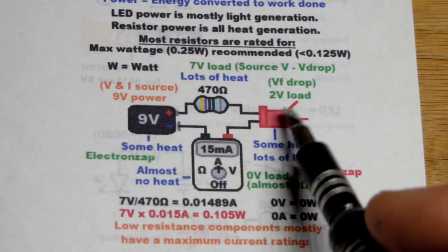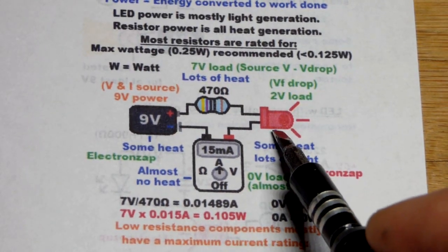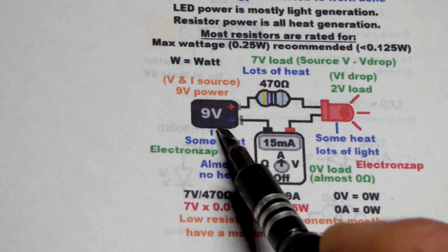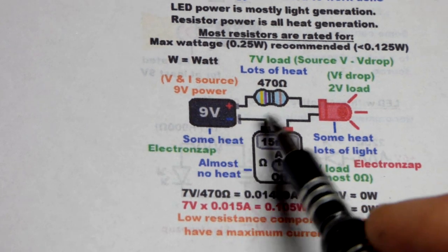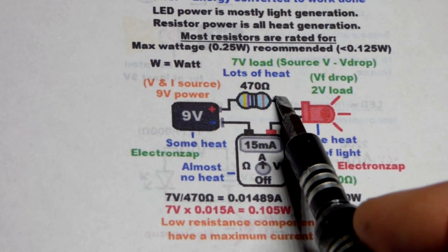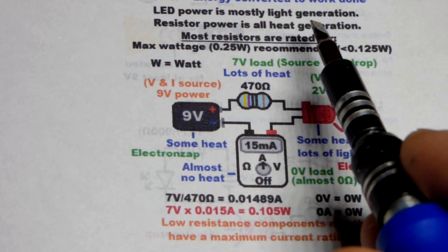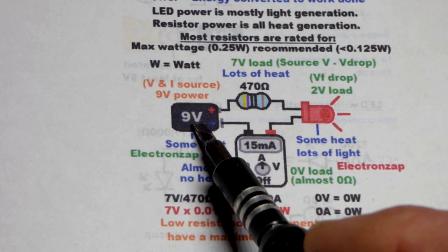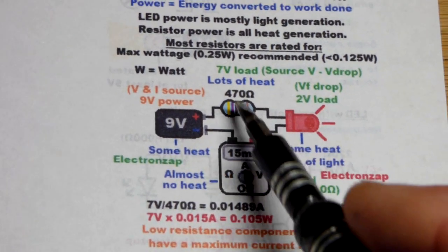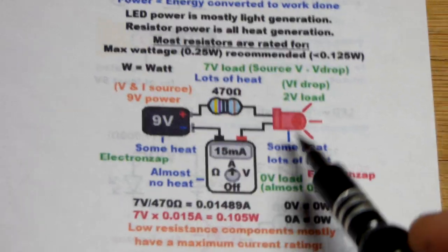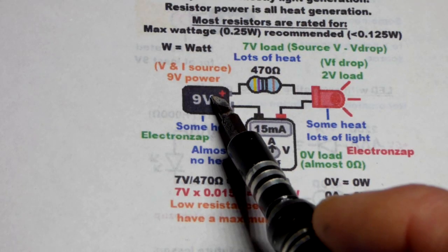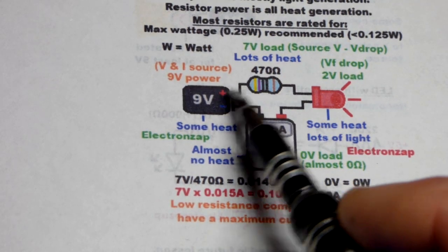So, as we said, we just need 2 volts to light this LED. And therefore, 9 volts is kind of a lot of voltage. We have 7 volts where it is not producing light. 7 volts is going across the resistor right there and just turning into heat. So if we had a lower voltage source right there, then we would not be wasting so much power as heat. That power is a little bit complicated, but hopefully that makes sense. You want to limit as much waste heat as possible.